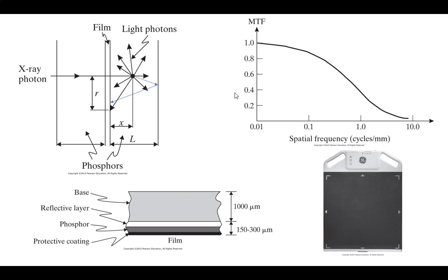The spatial frequency you can kind of see coming in here, right? Because of the blur, right? Any blur like that, a Gaussian type spread, is going to be a low pass. So this shows you kind of where it's at, right? So cycles per millimeter, so these are inverse millimeters, right? So you're figuring your minus 3 dB point is usually somewhere around like that 10th or so. So it just gives you an idea of what's going to happen with them. Make sense?